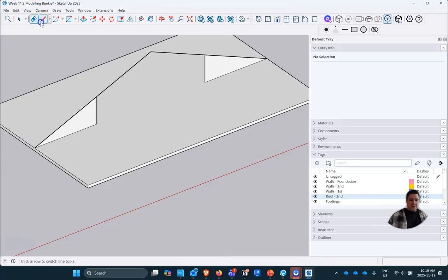And so going in the other direction, let me pick the midpoint. We don't actually have to pick the midpoint, but we'll do that. So let's type in 12 feet here, and let's go up. Let's actually go up 4 feet instead of 5. So we'll actually have different roof slopes on different sides, which is not necessarily abnormal, but typically you like to keep them the same. And so when we looked at our other method I did in the other class, it's